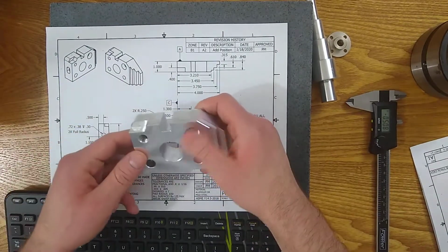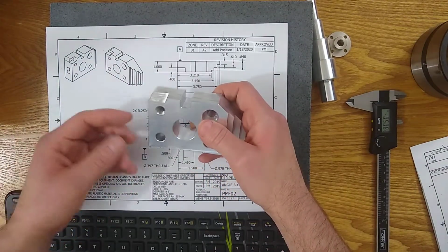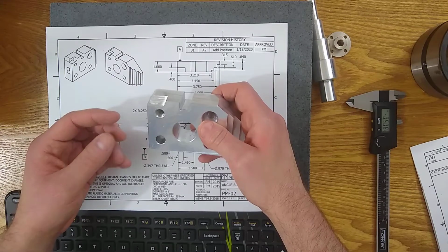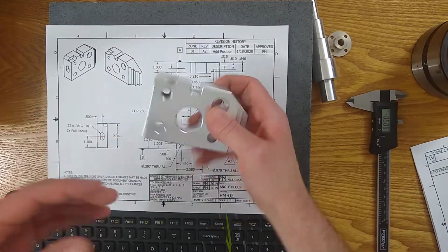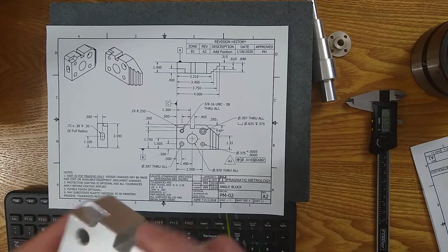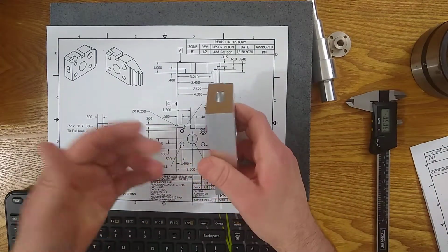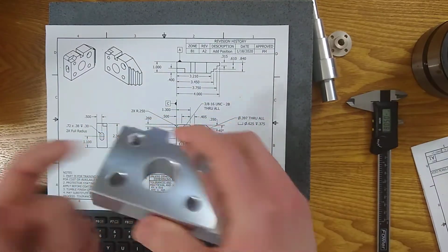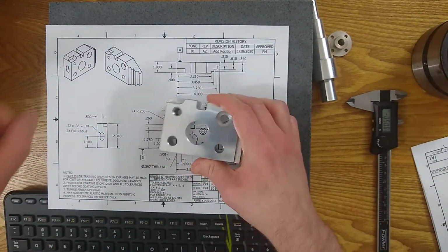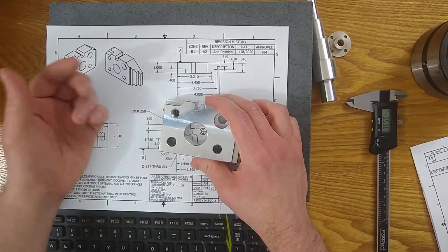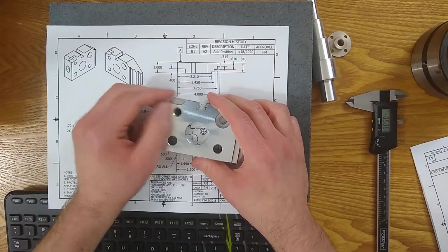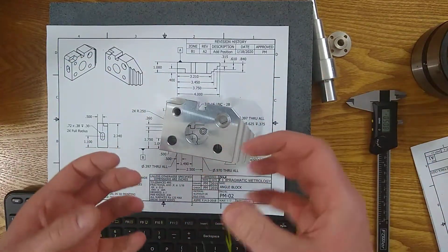Same thing with crest, flank angle, and other parts of the thread. As inspectors, even with internal and external threads, it's difficult to verify that. You need special equipment, and if it's internal, it's next to impossible. What you can do is verify the cutter with some sort of optical method. But for the most part, we have go, no-go gauging.